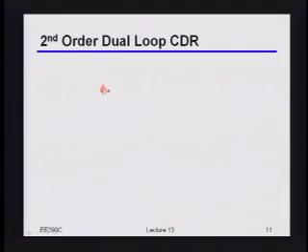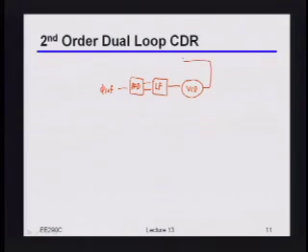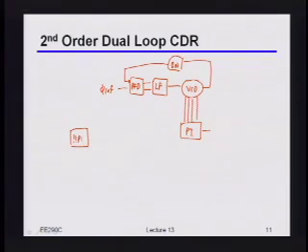Okay, so again, we're going to have some reference clock. We're going to have some main so-called clock generation PLL that we use to generate that reference clock. So again, our standard PFD, loop filter, VCO, of course, feed that back. Then divide by some n, feed that back to there. Then again, I'm going to take the multiple phases out of that VCO and feed them into some phase interpolator. And of course, just like before, I'm still going to have some bang-bang phase detector. So this is my data, and feeding into here is my either data or edge clock. Okay?